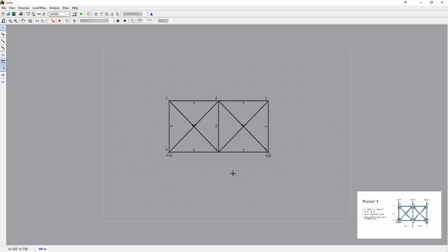To make this structure understand that we have created truss elements, we need to release the moment on all joints. That is why the only force that can be developed in those elements is the axial force, which is exactly similar to the truss elements.